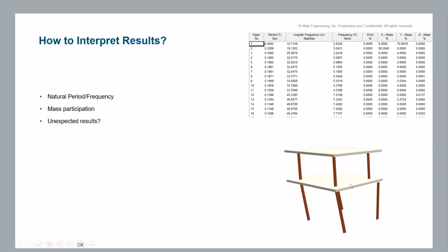So in this example right here, we can see an example where we've got a two-story frame with a slab on top, and for the most part, all of the structure is kind of oscillating in the same direction. But here we notice that there's a column that didn't go along for the ride. And this may be difficult to spot within the building of the model because everything is nice and plumb. We're not having any deflection. So we're kind of expecting it to look like it would be pointing straight up as it is currently rendered.